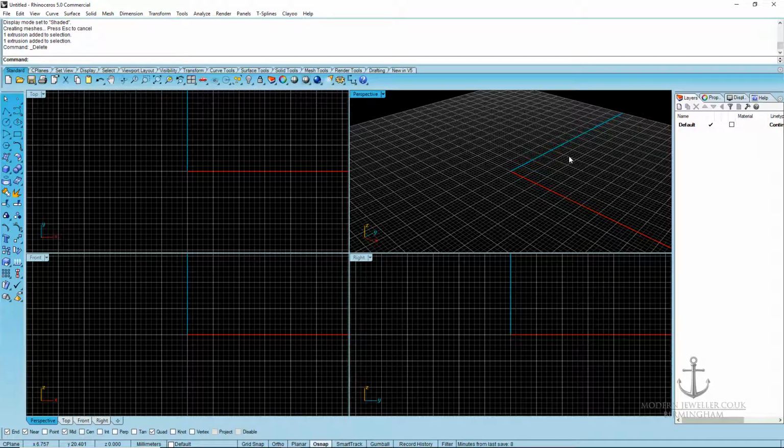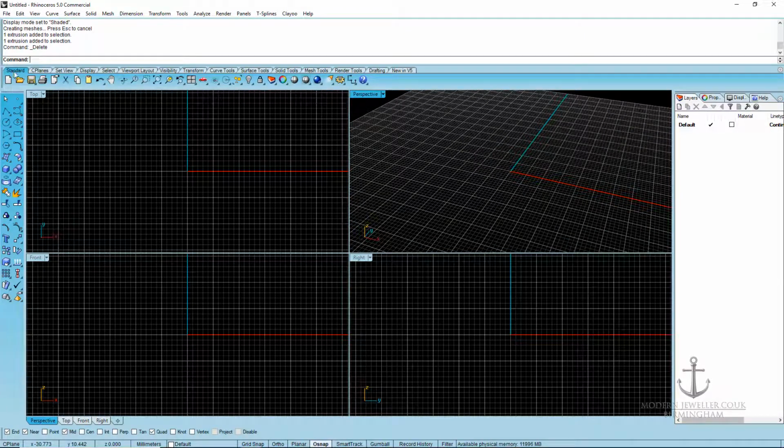Viewports navigation. In this video, you learn how to navigate in viewports. Before that, I want to create a box inside the scene. Be sure the standard tab in the toolbar is active. Then in the sidebar, click on the box button.